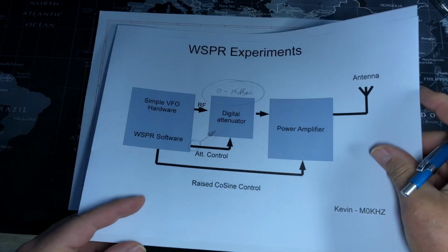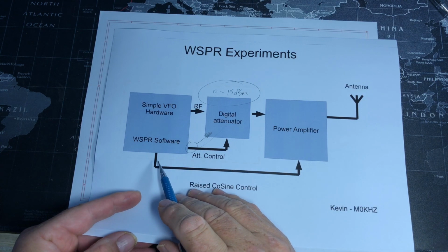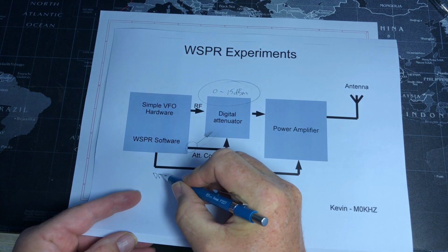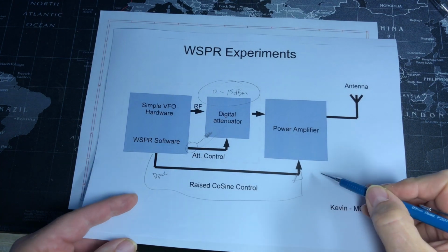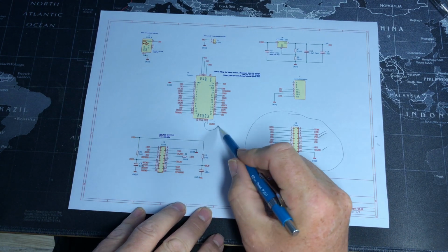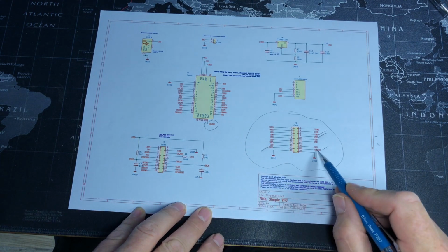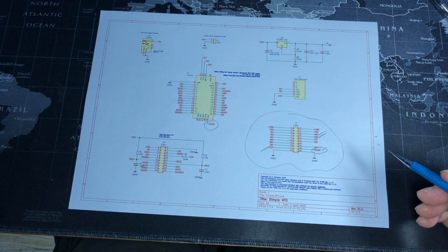And note, I'll also need a DAC output from the Teensy to feed the power amplifier eventually. And fortunately, I've taken that DAC output to the rear header as well. So the hardware will cope.